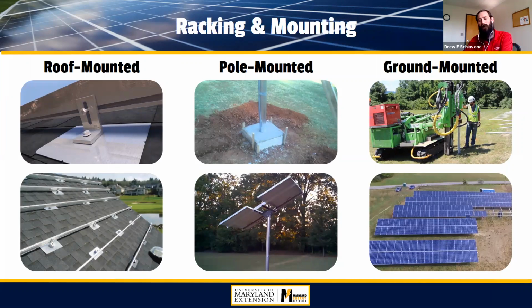So the first would be looking at the mechanical side, just the racking and mounting systems available. There are no limit to the different options that you have available for mounting. I shared a couple examples. The one on the left is for roof mounting systems, whether it's on your home or a barn or poultry housing, different options available. This particular example is flush on the shingles, and then you take an L bracket and the actual lag bolt goes through the roof, and so you have to be careful that water doesn't penetrate that system and into the trusses of your roof. But that's one example, and the railing then connects between those L brackets.